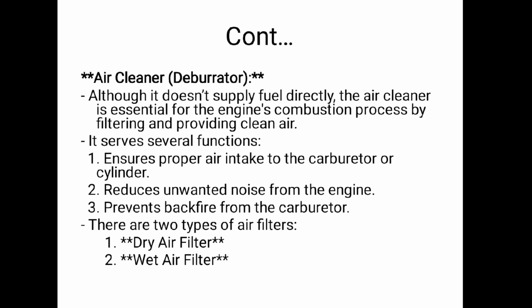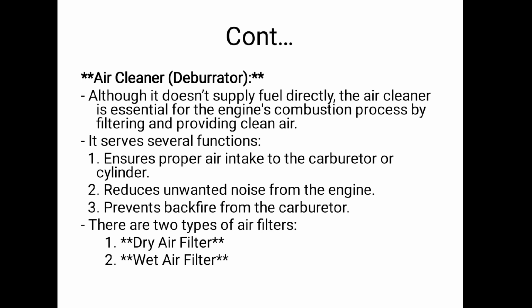So there are two primary types of air filter used in gasoline engines: the dry air filter and the wet air filter. The dry air filter is designed to trap dirt and debris using a porous material, allowing for easy replacement and maintenance. Conversely, the wet air filter employs an oil-soaked medium to capture contaminants, requiring periodic cleaning and re-oiling for optimal performance. So this is how these two types of air filter work.